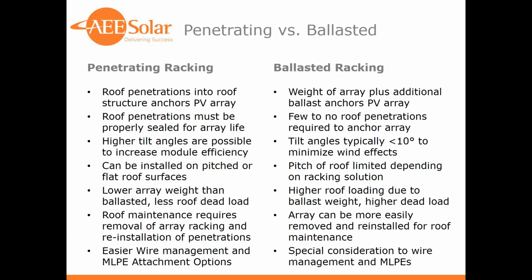So, advantages of penetrating racking. Roof penetrations go into the roof structure that anchors the PV array, whereas with ballasted racking, the weight of the array itself, the modules, plus additional ballasting and any anchors keeps the array in place. For penetrating racking, we have to make sure those roof penetrations are certified and sealed for the entire array life. With ballasted racking, we tend to avoid that by having few or no roof penetrations.